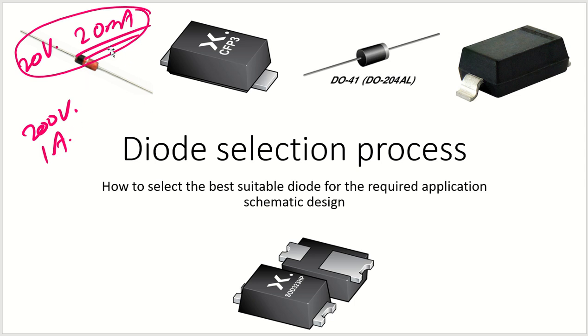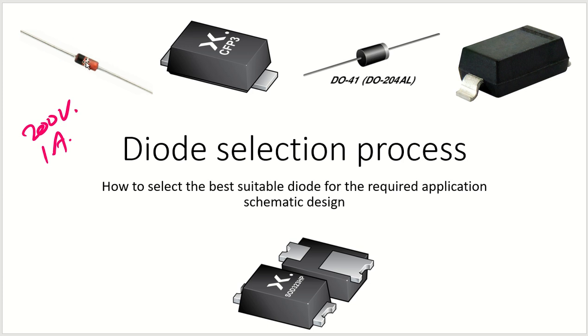So you can see a lot of different sizes are shown here, like DO45, DO35 package, DO41 package. There is always one more thing. You can see there is a notch that is shown here. So the notch means that it is the cathode. So hope you know the diode is like this: this is my cathode and this is my anode.